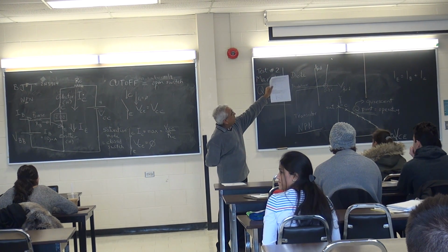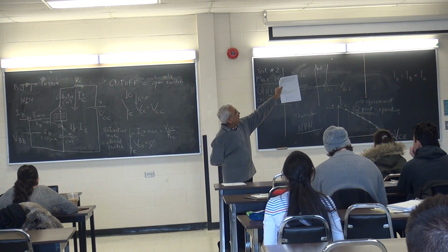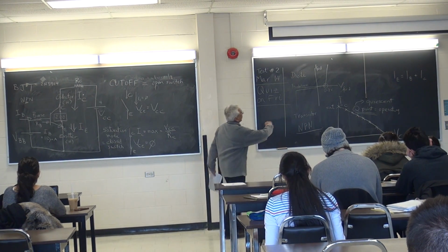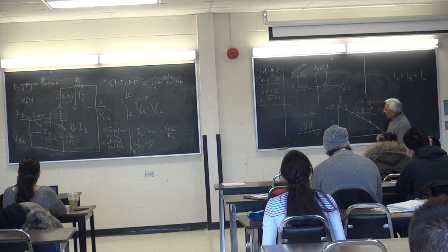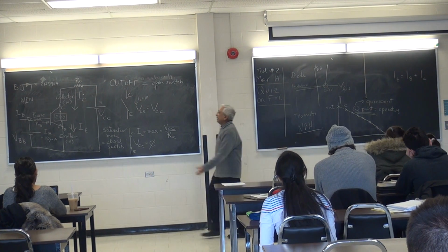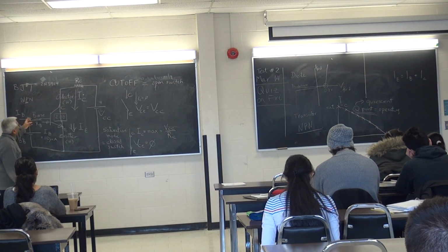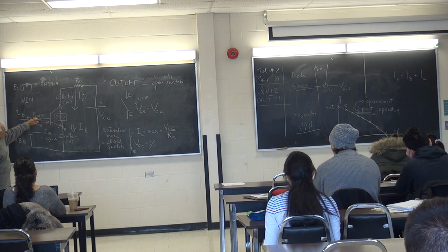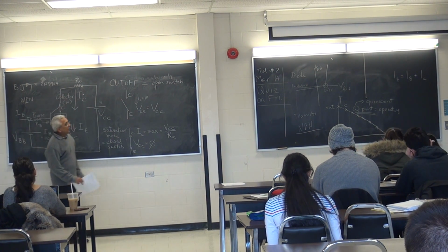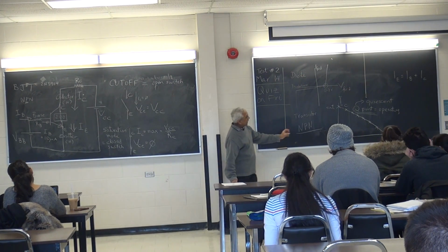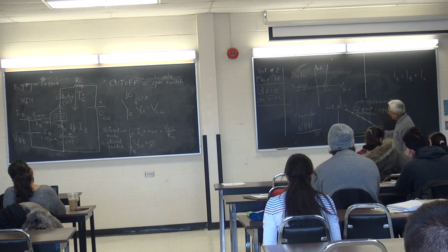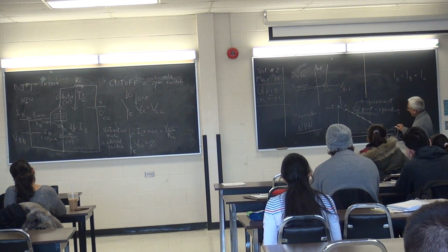Let's look at the graph at the bottom of page 9. What the graph at the bottom of page 9 shows is all these other lines. And what are those other lines? The other lines represent the base current, which is saying that I have to have this base current in the first place to cause the collector current to flow. So what it's showing is I'm starting out with a small base current. So a small base current is shown like this, 100 microamps, let's say.